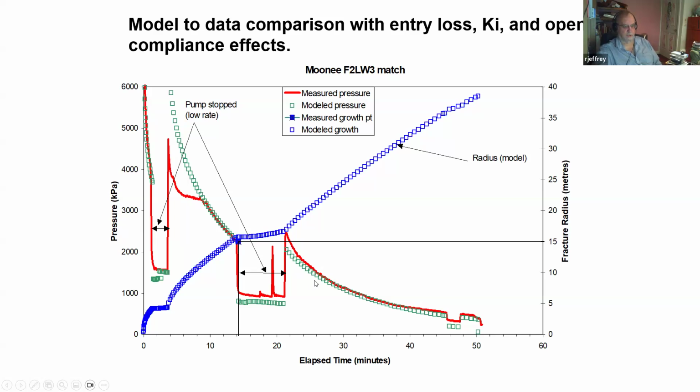So the common aspect of these treatments were that they started at fairly high pressure to break down the open hole in the roof, but the pressure then fell quickly, indicating fracture growth and opening of that fracture, with the fact that there was a free surface less than 10 meters away, allowing the fracture to open more quickly than normally would be seen in a deep fracture.